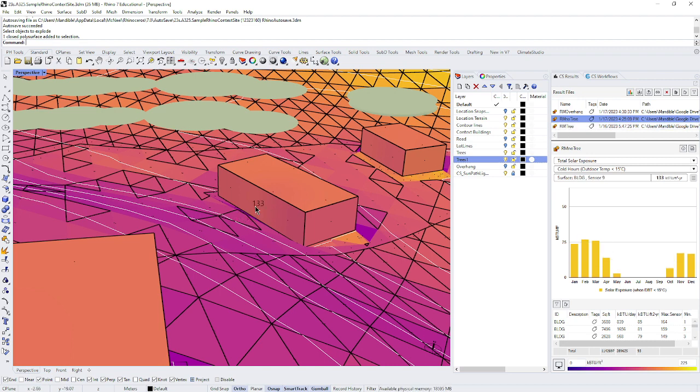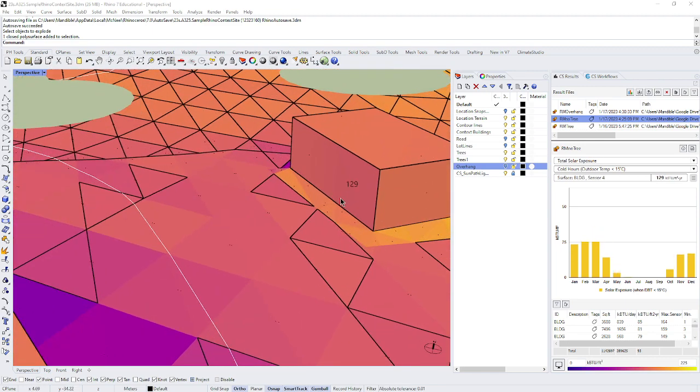And if my goal is to get sun onto this south facade, which is when you'd be heating, when the sun's going to be low in the winter and accessing the building to heat it if I need heat, then I would need to get rid of those trees according to this model. Let's say I didn't want that and there weren't trees and I wanted this to be shaded. Well, what happens if I put an overhang on? I just remembered I changed this when I was playing around with it. So let's just go look at this facade. This is where I have the overhang.